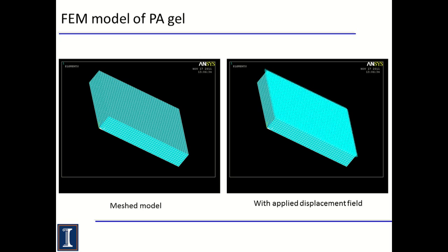A set of elements is referred to as a mesh. A problem is defined in terms of loads, stiffness, and displacements and is solved by setting up a large number of simple algebraic equations at nodal points for each element and combining for the entire mesh. We make use of a commercial FEA software called ANSYS.